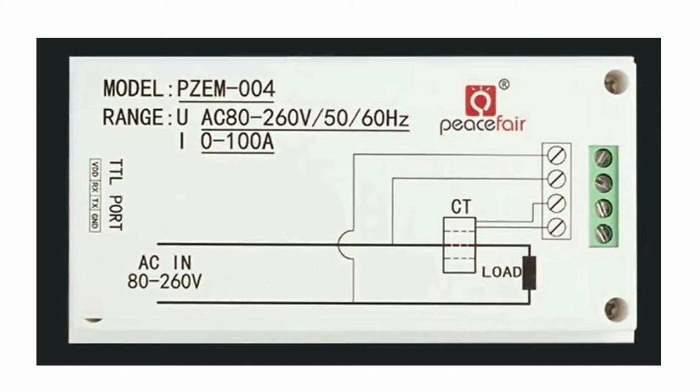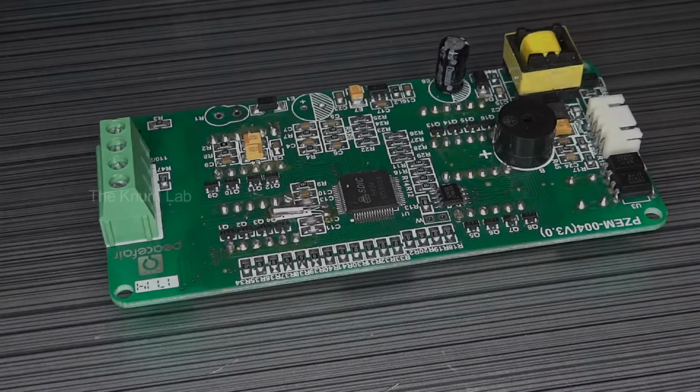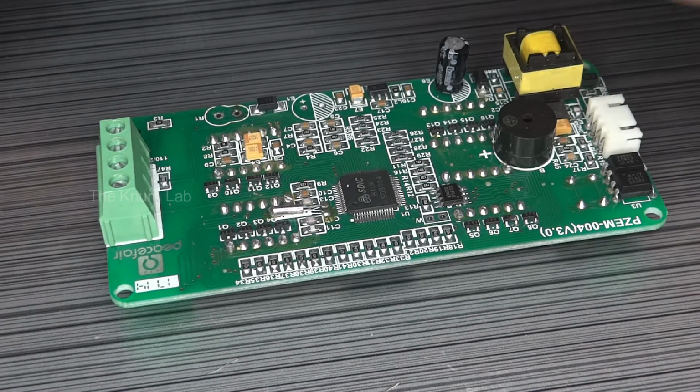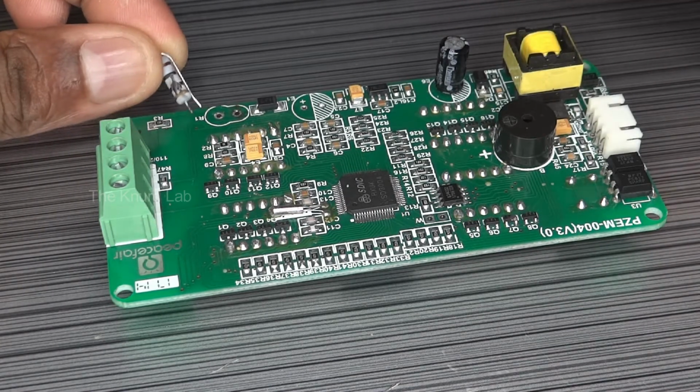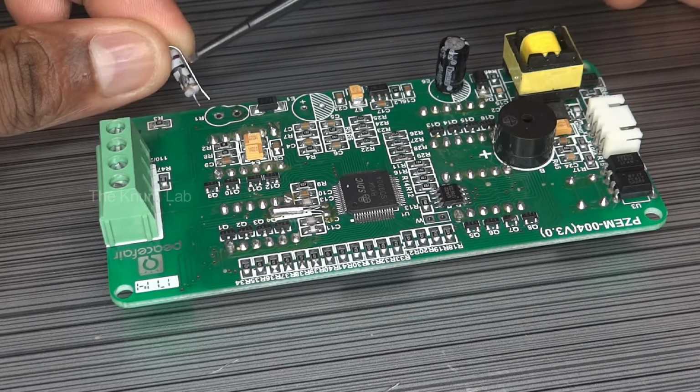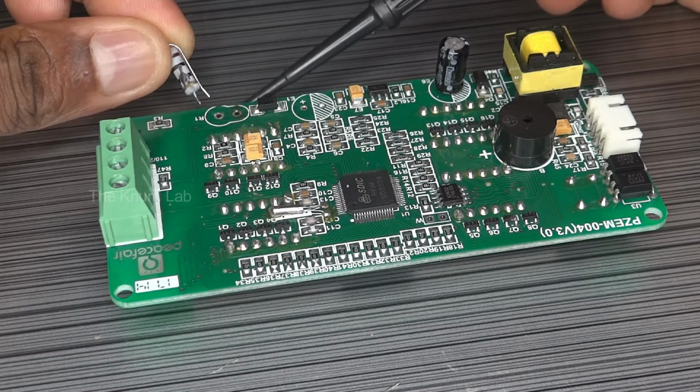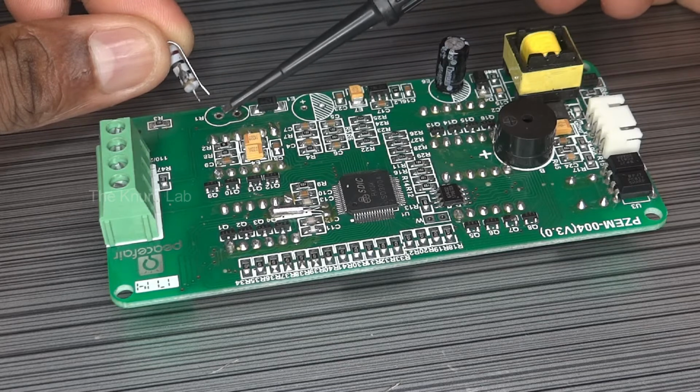There were no surprises there. As always, poor component selection and bad design were the reasons that led to its smoky, obnoxious demise, if I may call it so. For an energy meter that's supposed to work 24/7, the power supply section could have been something better than a half-wave rectifier, which is expected to rectify 230 volts AC continuously for its lifetime. It's not a surprise that the electrolytic capacitor decided to go ballistic.